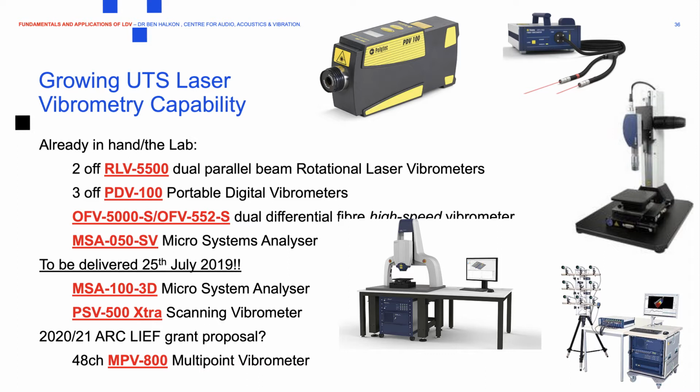To be delivered in about a month's time, a microsystem analyzer which makes measurements on a micro and nano scale of structures in 3 directions with sub-micron spatial resolution, sub-picometer displacement resolution, and a scan range of plus minus 50 degrees in XY. So we actually put the sample on this bed and we move it around underneath this microscope system, which has got 3 independent laser vibrometers in it, and it resolves for us into 3 orthogonal directions automatically. And a PSV 500 macro scale scanning vibrometer, which is the first in the country that will have infrared light in there.